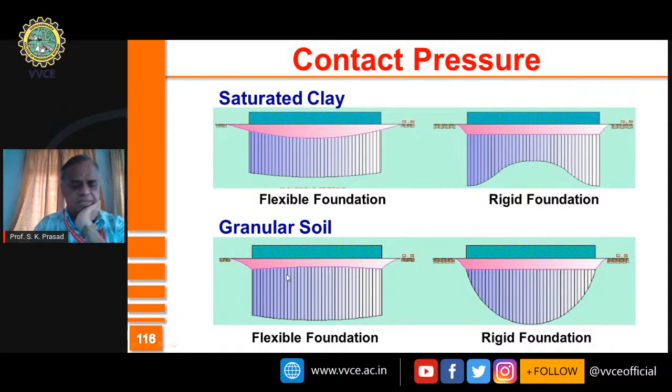On the other hand, if it is granular soil, you will see less pressure here, and the footing will experience a bending, something like this, more bending on the sides.